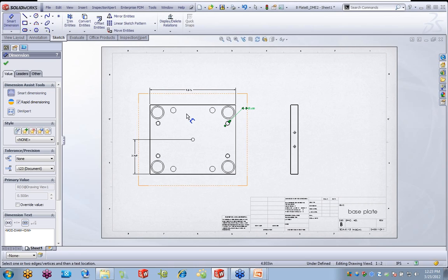Now, in cases where you're placing dimensions to the right or left of the model, I'm going to do a couple of these here, the software can also reposition dimensions. And the spacing that it's using to reposition them is really based upon, again, those dimensional values and options that you have specified. Okay, so it makes it really easy with rapid dimension to flop some dimensions on here real quick. Okay, so there's a little bit about rapid dimension.